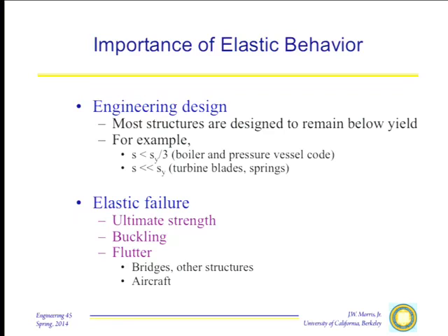Interestingly, we started a program here, guys, 12, 15 years ago. The ideal strength of a material, elastic instability, is about the only mechanical property that you can, by God, calculate from first principles. Given advances that happened some years ago, you can take the crystallography of your material, you can throw it in a computer, you can crank and grind and solve Schrodinger's equation, and actually predict the elastic stress-strain curve all the way up to failure. And in fact, I don't have time to go through it in this course, but there are some fascinating things that you learn by just exploring the ultimate strength of materials.